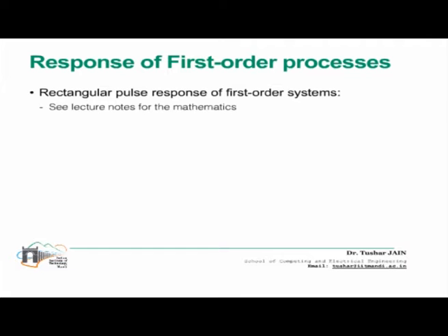If I put this U of s in the first order transfer function, I would have, I forgot the minus sign. Again, I will take the partial fraction and then the Laplace inverse, so that I could have the time domain representation of the signal y(t). This is how I can do it.